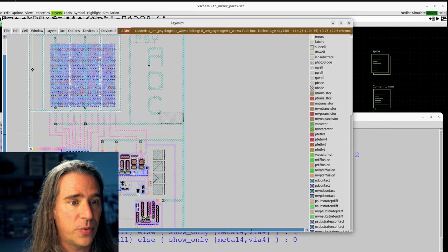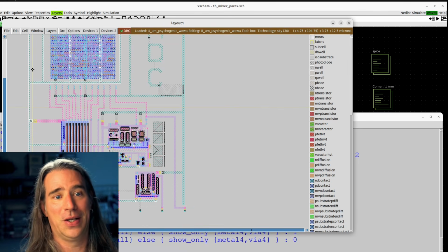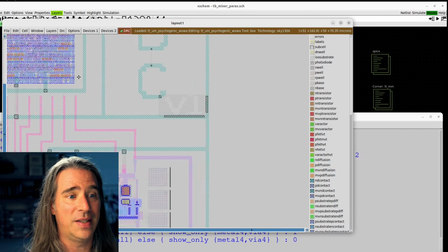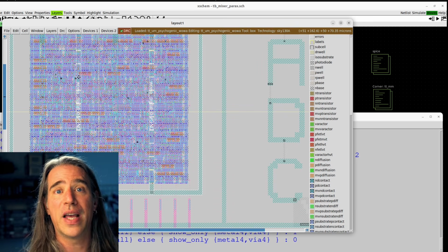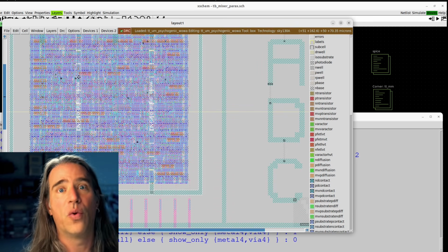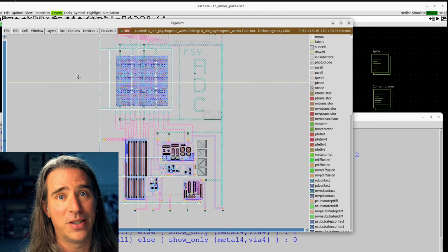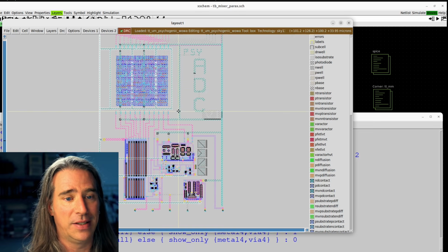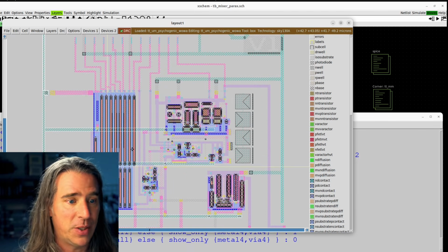One thing I would have changed would be to put in more bypass capacitance, because in the digital world, where you're not filling anything, you get a whole bunch of bypass caps for free. The system takes care of it. In analog land, that's your problem. So yeah, next time, more of that. That's pretty much it on this front.